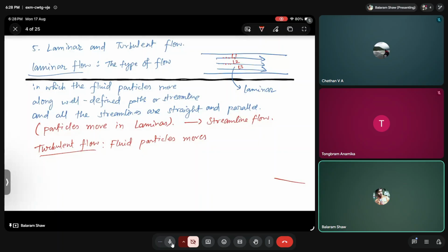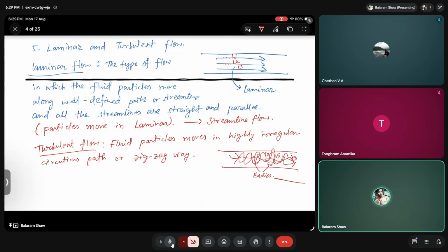Turbulent flow can occur when a steep hydraulic gradient exists, for example near pumped wells, or in rocks such as basalt or limestone, which contain large underground openings or cavities. There, turbulent flow is mostly seen. Or if some hydraulic jump is there, we'll maybe see that in the later slides.